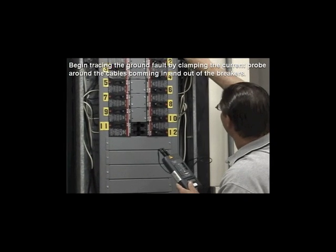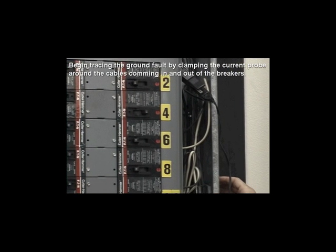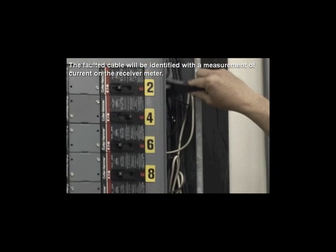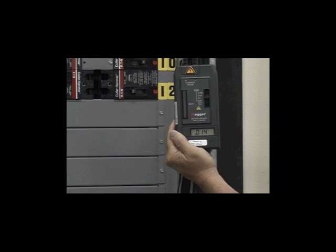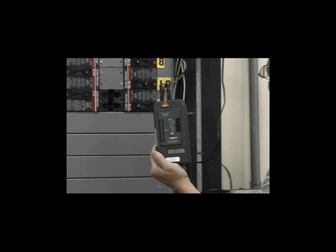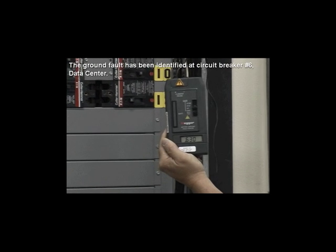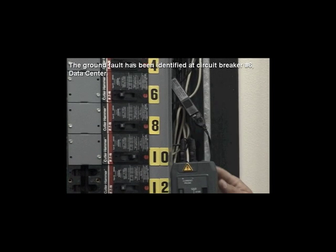Begin tracing the ground fault by clamping the current probe around the cable coming in and out of the breakers. The faulted cable will be identified with a measurement of current on the receiver meter. The ground fault has been identified at circuit breaker number 6, the data center.